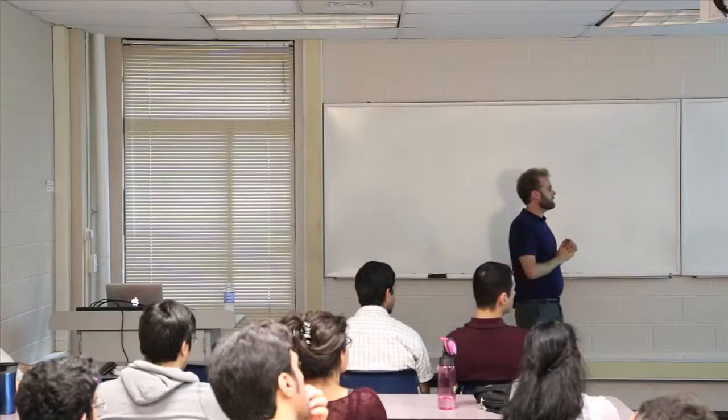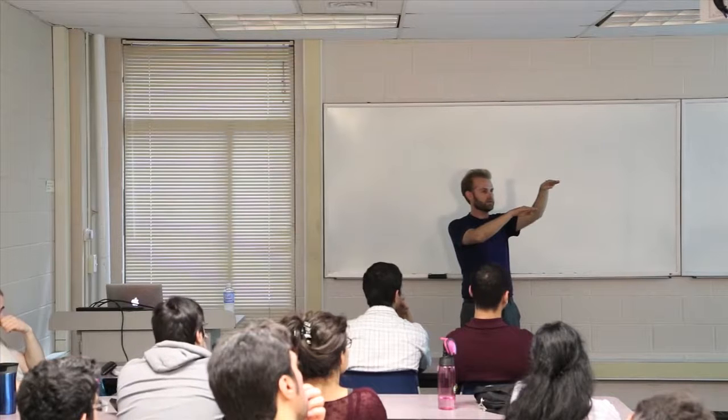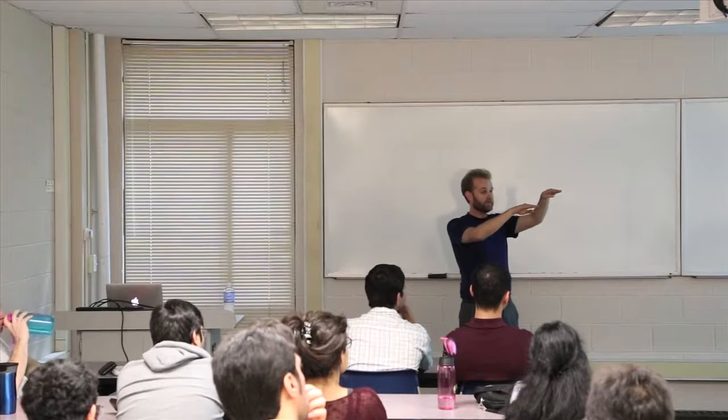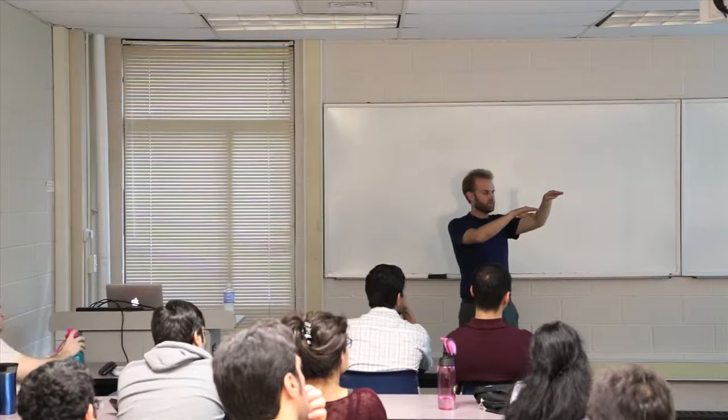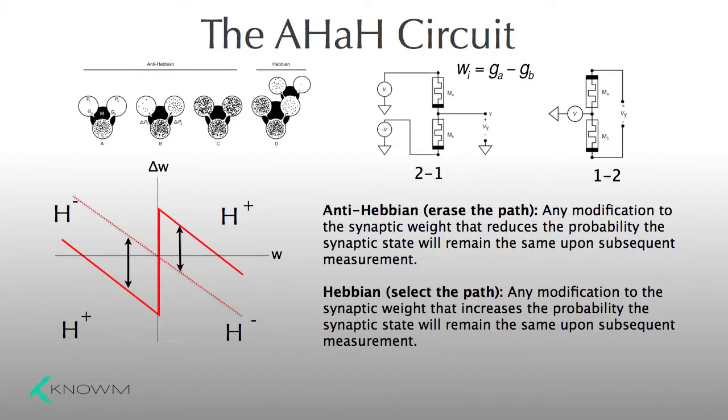Okay, so how do you do this? Well, if you do it in an unsupervised manner, you can imagine that, say, they started off and one was like this, it was positive. You read it, it brings it a little closer together, but then you reward the one that won. So if it came out positive, then you say, well, I'm going to reward it, and I'm going to make it a little more conductive. Okay, so that's Hebbian learning. So this is anti-Hebbian learning, and that's Hebbian. So if you reinforce the state, you're Hebbian. If you degrade it, you're anti-Hebbian. Anti-Hebbian in this case is passive. You don't have to do anything. Hebbian learning, you have to apply sync. And you put those both together, you end up with this little Zorro-looking rule, right?